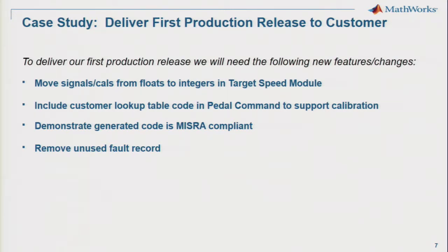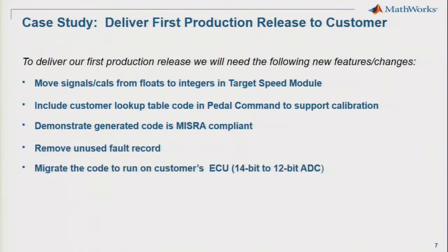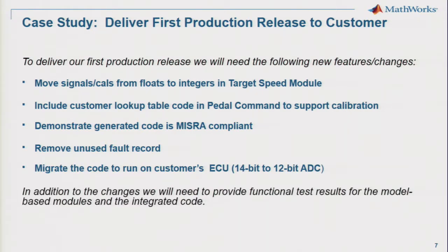That's correct. The hand code modifications are very minor, which is removing unused fault records, and also making minor changes to the new ECU to read 12-bit instead of 14-bit A2D data. In addition, the customer also requires us to provide functional testing on the integrated product. Okay. I'll hand it over for the model.